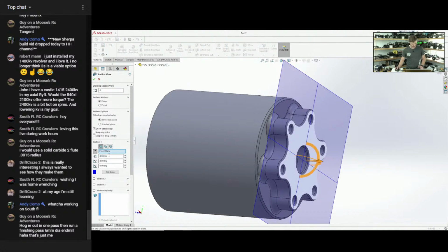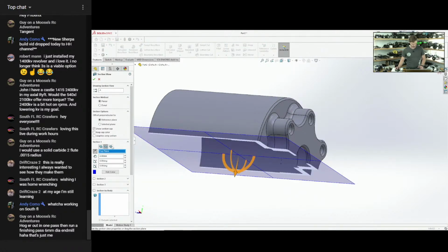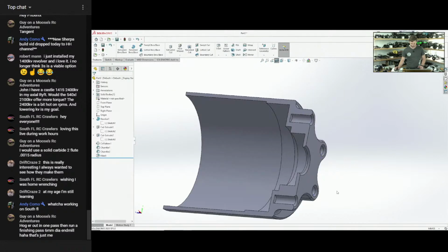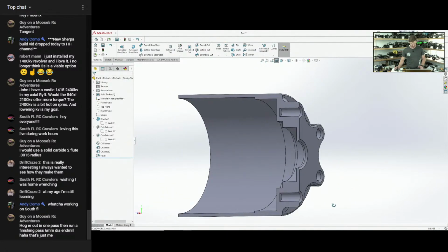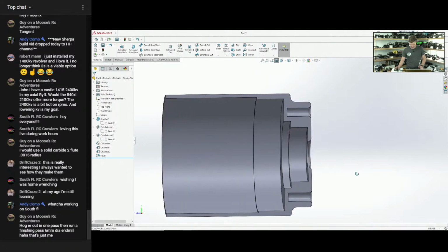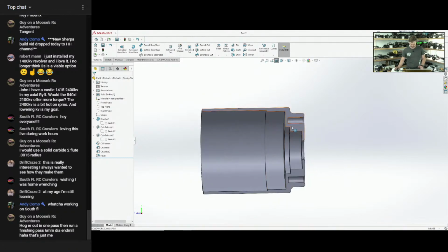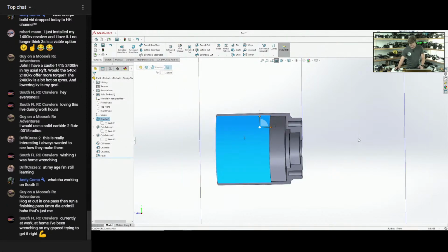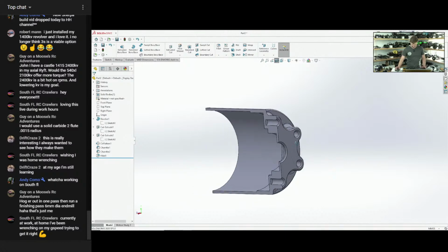And let's look at the selection here. So as you can see, we got the blind holes going in. They won't be able to be threaded all the way down, even with a blind tap. There's still going to be a small section where they can't reach. And, you know, it's a bunch of heaviness that's going to be in here. There's our bearing pocket. Here's our clearance for the bearing pocket. And then our clearance section for our stator wires on a distributed wind, like I said. And then the section that is going to actually have the stator slide in. There we go. We are getting much closer.